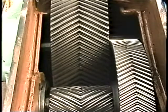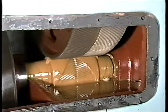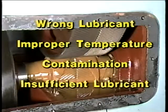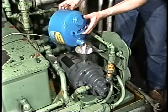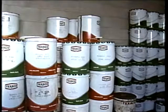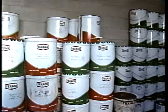Problems with lubrication or lubrication systems can soon lead to problems in a gear set. Now, gear lubrication problems can be divided into several general categories. The basic causes of lubrication problems for gears include using the wrong lubricant, improper temperature, contamination, and insufficient lubricant. One type of gear lubrication problem can occur when the wrong kind of oil or grease is added to a gearbox during routine maintenance. The improper oil for a particular gearbox may not have the proper viscosity or oil additives to handle the loads, speed conditions, or temperatures that the gear set operates under.